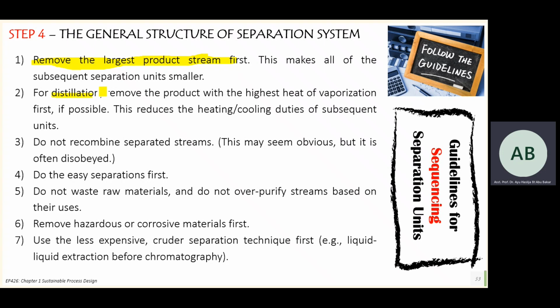Now for distillation, remove the product with highest heat of vaporization first, if possible. Okay, the most volatile first. Do not recombine the separated system. Perhaps you say it doesn't make sense. After separating, then why need to combine back?